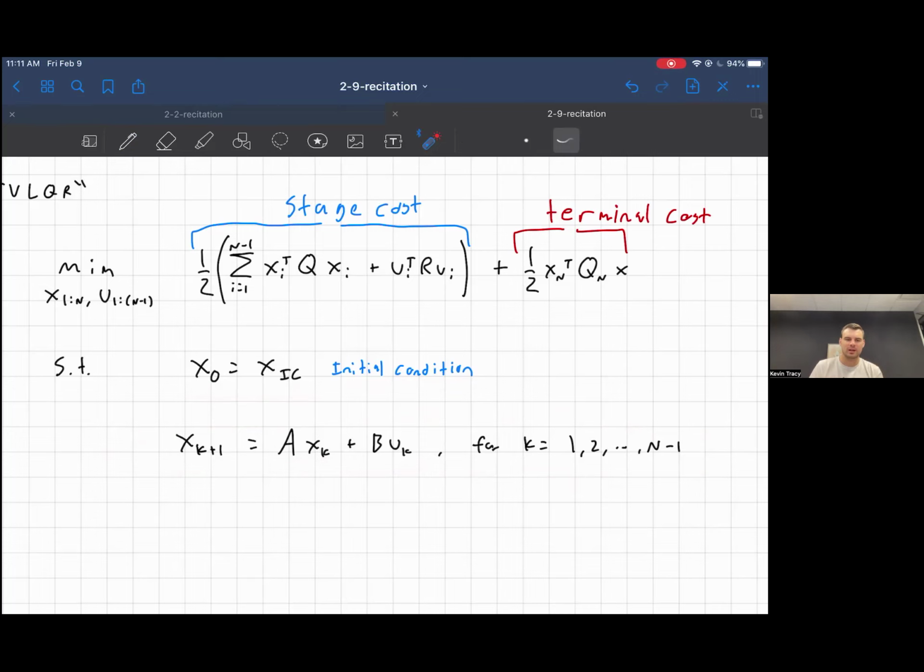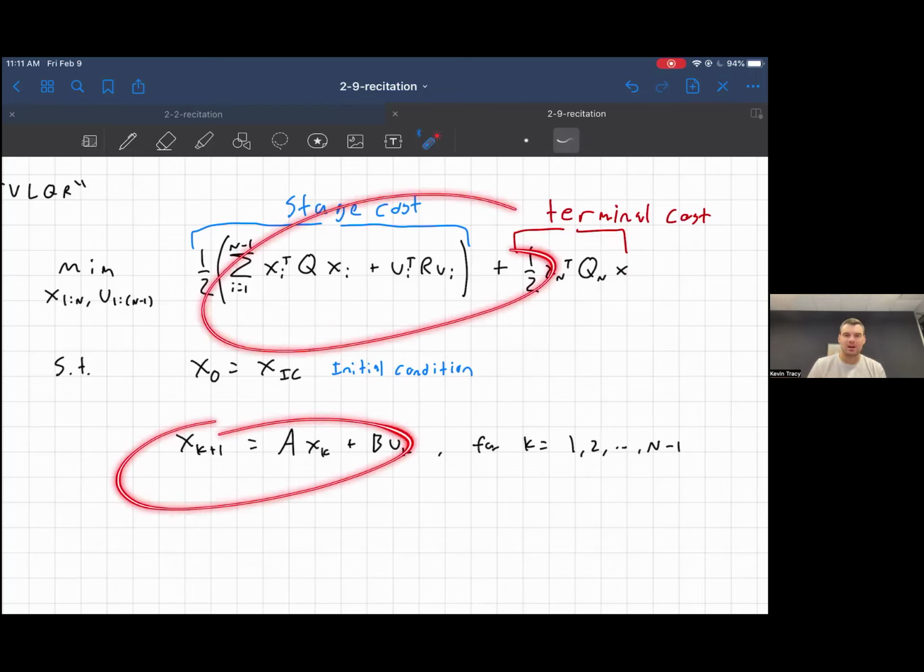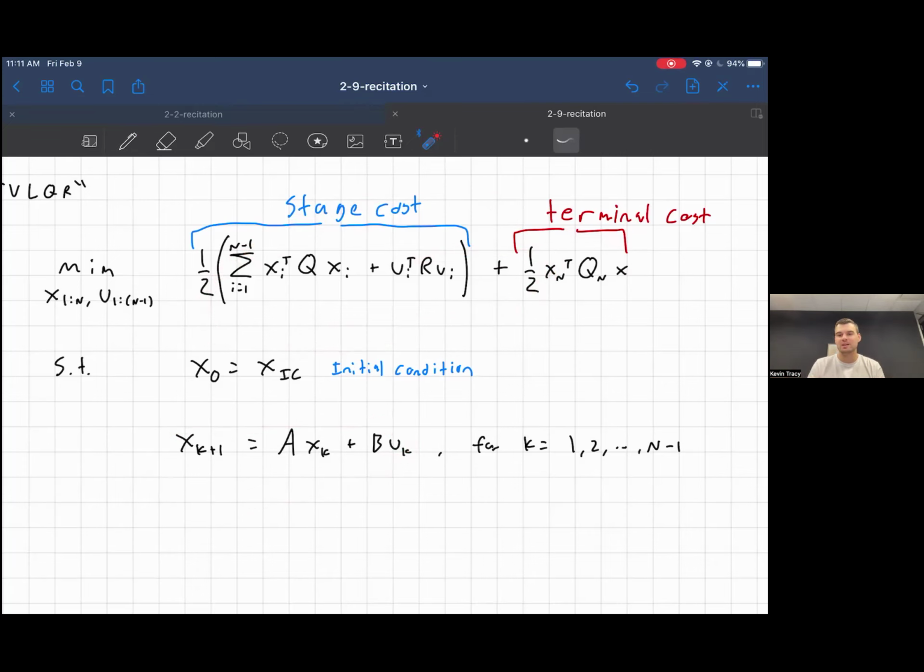So at a very high level, what we're looking at here is that I want to solve for a controller. I'm given some system, you give me the dynamics of some system, and then we give ourselves this cost function. And I'm trying to use convex optimization, or just generally numerical optimization. I want to formulate my control problem as an optimization problem. And that's the theme of the whole class: I always want to take my control problems and do some concrete numerical optimization to give me what my control input should be. And so a really nice way of doing this is I just take the dynamics, I take my cost, and I just put it into an optimizer, and I say, give me the solution to this.